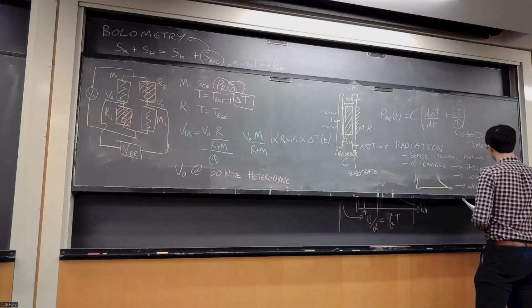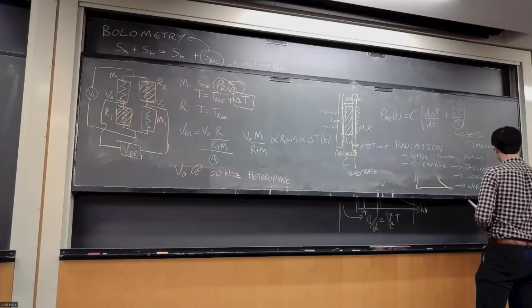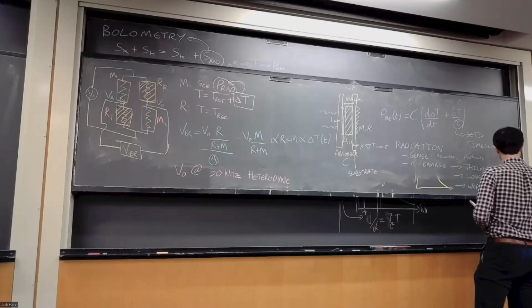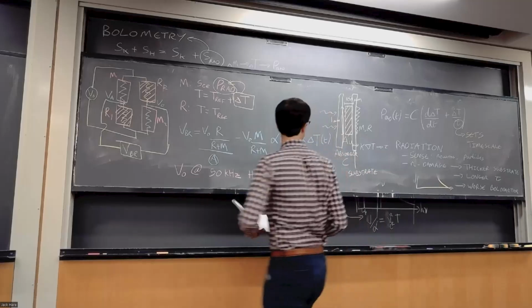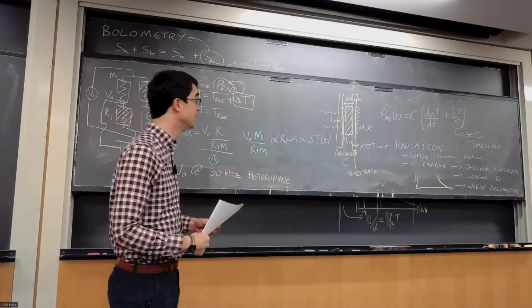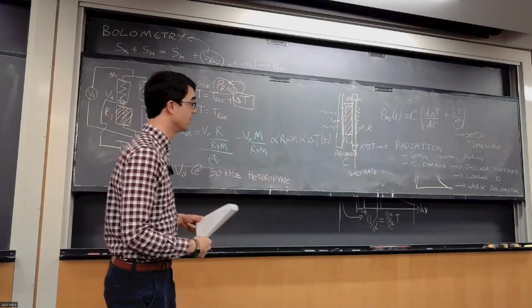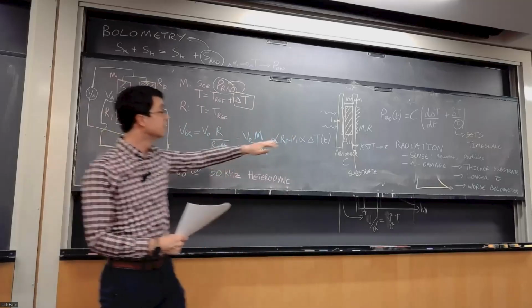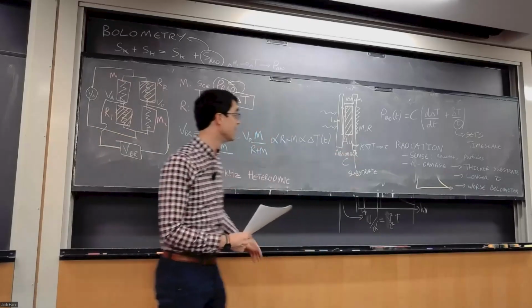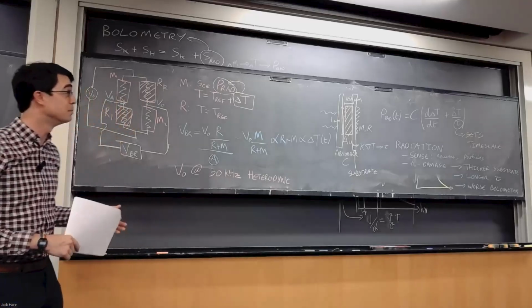So ironically, the bolometers that will be used on ITER are significantly worse than the bolometers used on existing devices, not because they couldn't work out how to make better ones, but because the radiation forces you into a regime where you can't use a good bolometer anymore. And I'm sure that SPARC will have exactly the same problem. Almost everyone in the world uses this design of bolometer that they planned on the ASDEX Upgrade in the 80s. No one has come up with a better system yet.